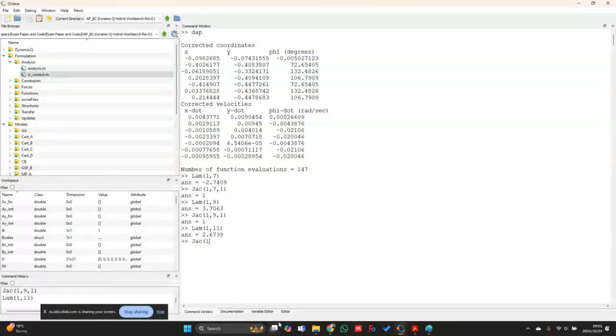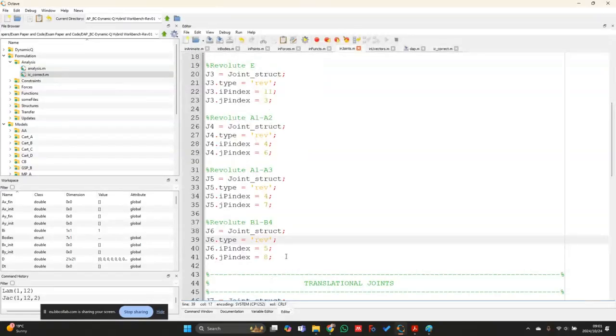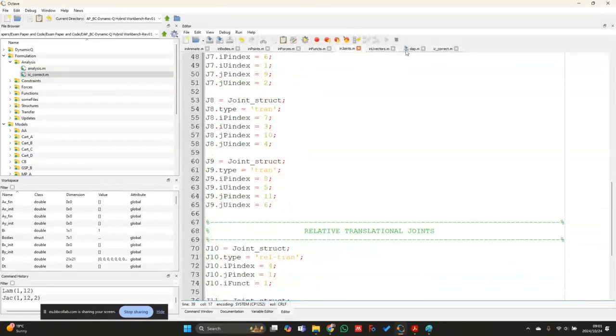I can just go and check Jacobian as well. So if I say this, and this is in the one direction again, so then I still get 1 out, so that's fine. And then in the y direction, it's going to be Lagrange multiplier 1, 12, and then Jacobian 1, 12, 2 is 1. Okay, so it's identically equal to the Lagrange multiplier, since I just have multiplied by 1 in this case. But I'm in any case going to include it in the formulation.